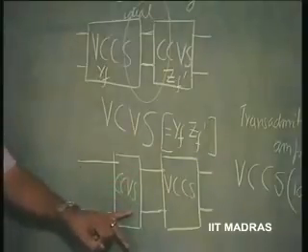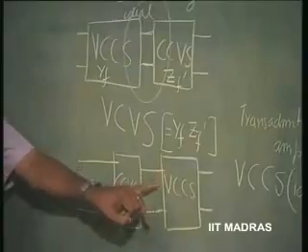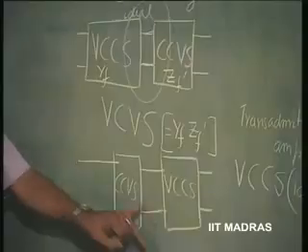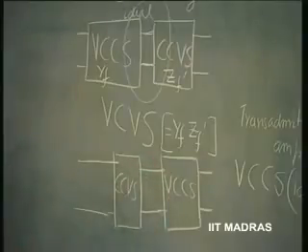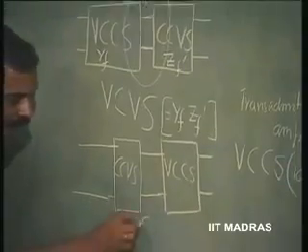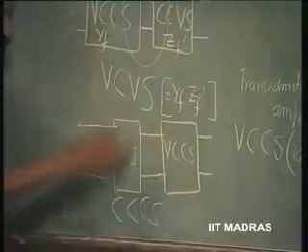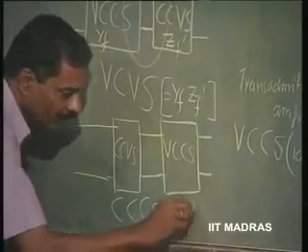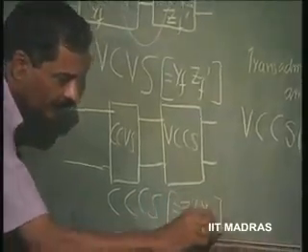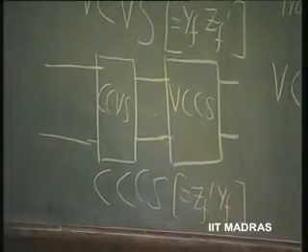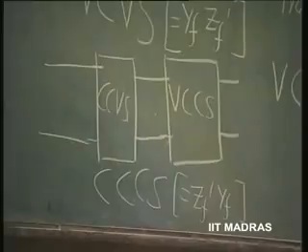This is a voltage source, that means source resistance is 0 feeding on to a voltage controlled block which is infinite impedance, right. So, very nicely matched here, and therefore, this is a current control current source with the same ZF prime into YF as the current gain now, instead of the voltage gain.